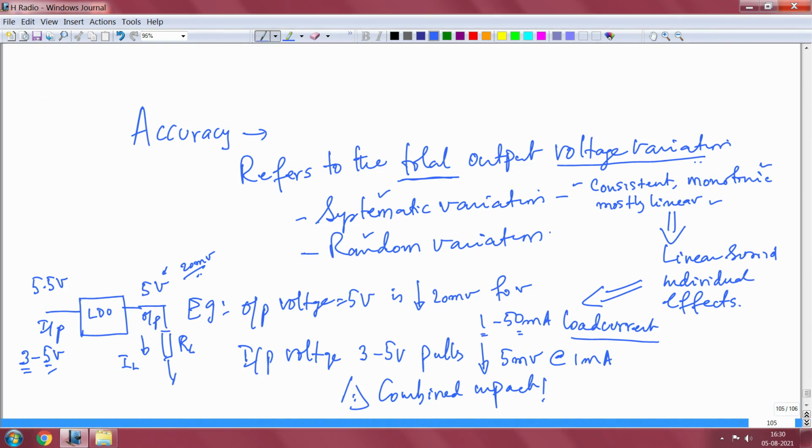Now, that small fluctuation is not fully seen due to the input capacitance. So I put an input capacitance so that the LDO does not shut off. For that small variation, let us say the output is down by 5 millivolts for a very short duration under a load current of 1 milliampere.